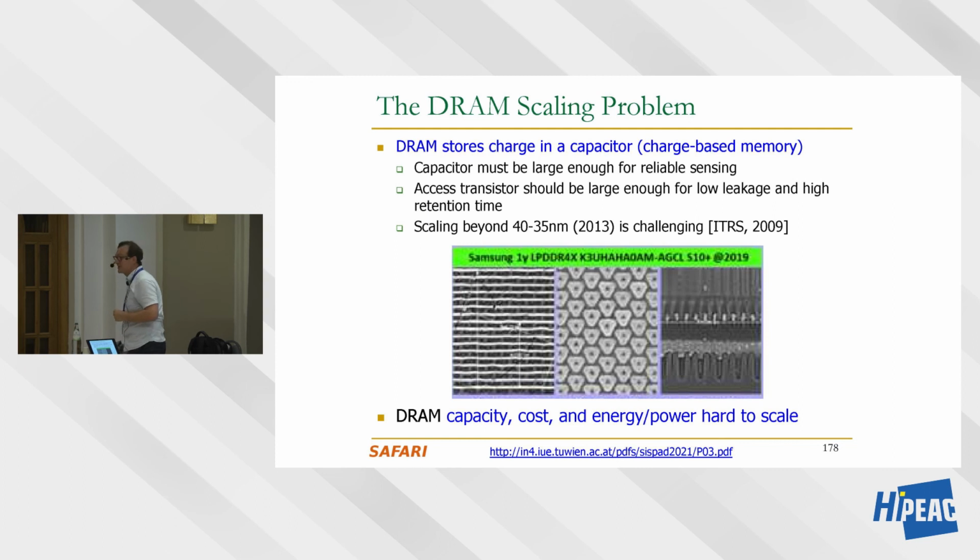Okay, so manufacturers have been actually doing a lot of heroic acts. So this is what DRAM looks like internally. This is a capacitor. They've etched the capacitor into the substrate. The length of this capacitor is maybe 70 to 80 times the length of this transistor over here. So this is another view, basically. That logical view that I showed you was very different from the real physical view. This is the access transistor over here. This is the capacitor, and then there's a bit line and the word line to access.